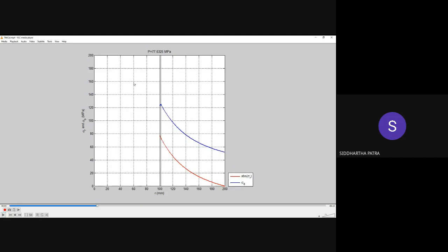Now let's say about 75 MPa is when you first encountered plasticity, and then this other radius C is now visible. What is happening is that inside C the stresses are now changing differently as compared to outside of C. And inside C, if I were to take the correct sign of sigma r, the difference between sigma r and sigma theta would be the same. But because I have taken the absolute value, their sum actually remains constant for a given pressure.